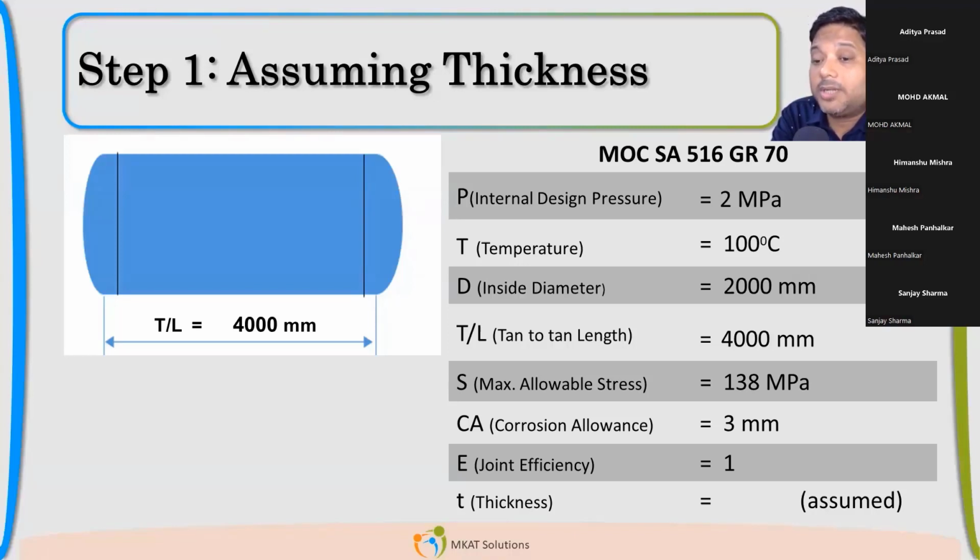Now here you have to understand that the vessel will experience external pressure only when there is an offset condition. It will not happen in normal operating. So whatever design temperature for internal you might have got from the client or process department is based on internal pressure, based on operating.